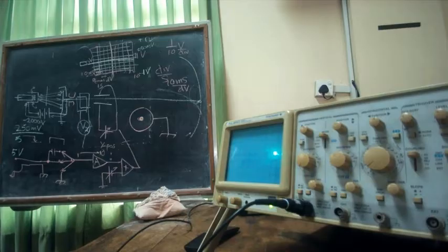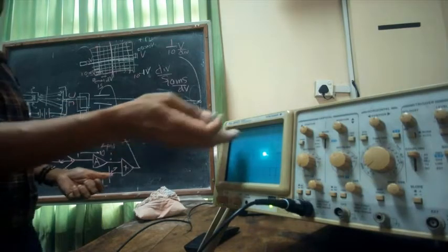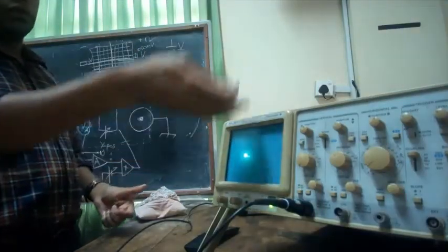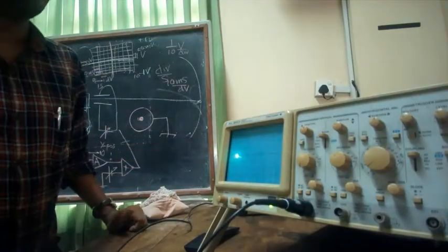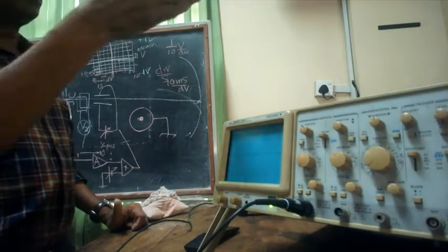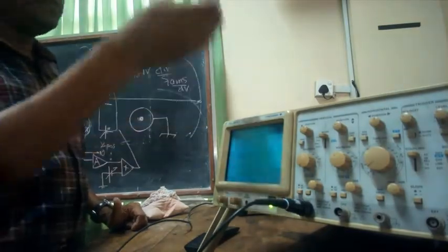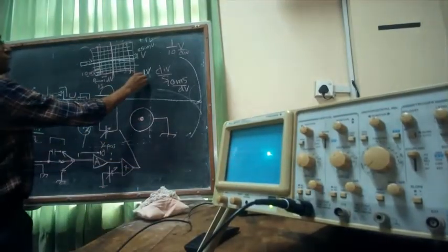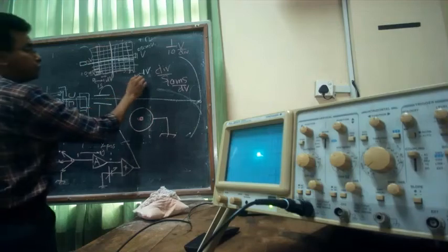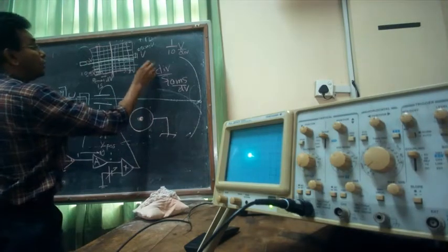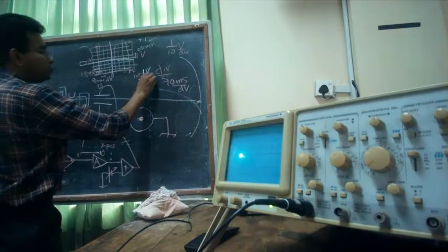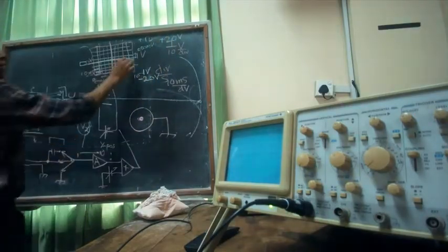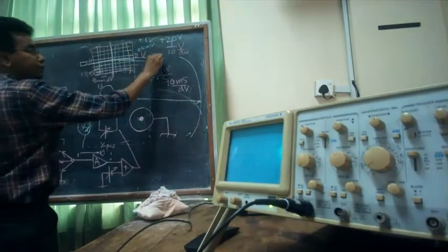So it's an attenuation in this case, but probably inside this, it's not 250 millivolts, it could be a much bigger value, right? Maybe from bottom to top, it could be 20 volts. Sorry, so instead of -1 to +1, if this was -20 to +20, let's say, as another example, then one division is 5 volts.